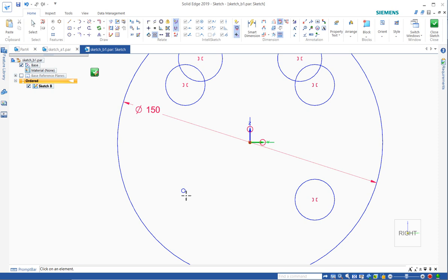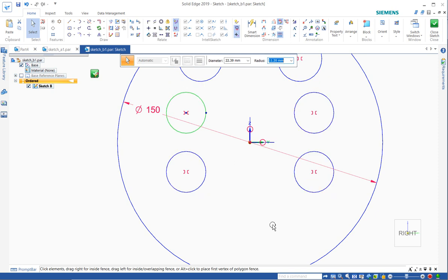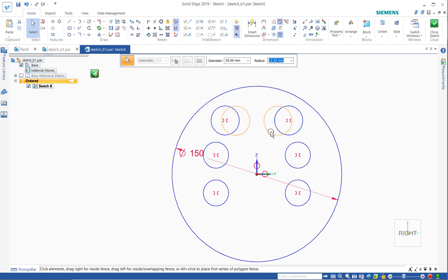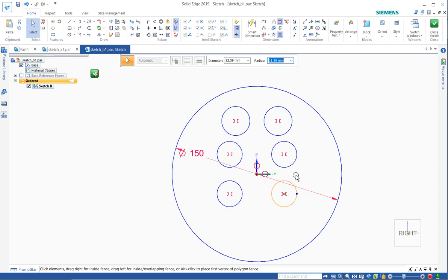This is causing a little bit of a problem, so I'm just going to delete that. I'm going to do it in the other order. The other order, I'm going to say, make this small element symmetric to that element. The first thing that you click usually is what moves. I don't usually focus on that too much, because if it moves, it's because it's under constrained, and you really just need to put more dimensions on there.